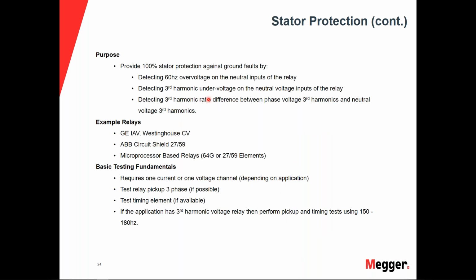The purpose, we kind of just went over this. The purpose was to be able to detect the third harmonic undervoltage, and allow us to get the 100% coverage using what's inherent to the generator itself.